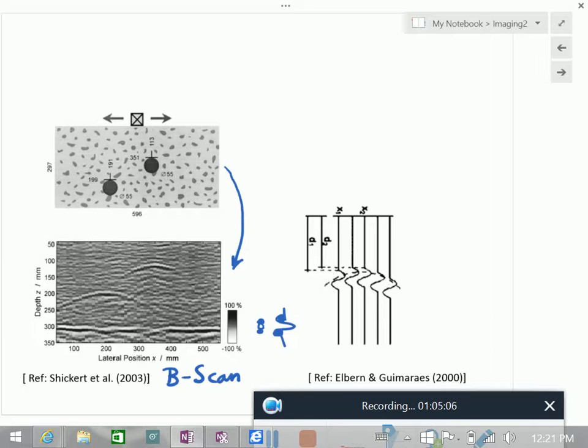But also, this is a big hole someone drilled into the, this is a lab at BAM where I was working. We just drilled a hole, and so if this was a real, not very perfect cavity, that is typically what you want to find, do you think it would be very easy to find this reflection? And even the location, exactly where it is, is not very clear. I mean, you can argue that wherever you get the maximum, or it is the closest to the surface, that's where it is. But remember, it's not like a continuous thing. You have it at different locations.